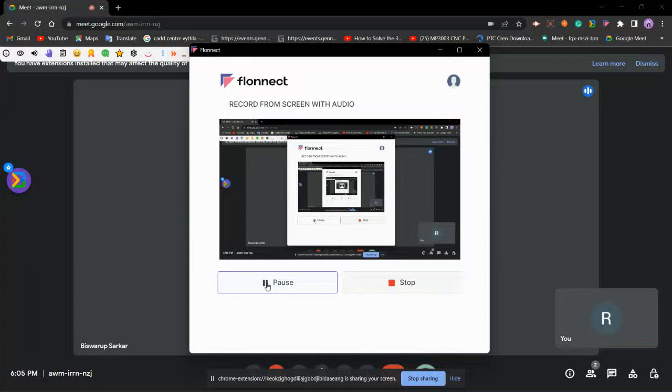And for starting any part design, we need some sketches. For that, go to the sketch toolbox, click on sketch, click on the plane in which we have to draw, and we can see axis and the tools. It is confirmed that we have entered into the sketcher interface. I'm drawing a simple figure here, just to extrude, similar to the way in which we studied in SolidWorks.